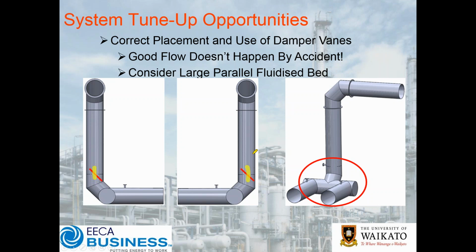And then what we were able to do was tune everything down with the VSD, and we had the airflow on both sides balanced with purely VSD control with a flow meter, even on both sides, to within less than 1% variation. So quite successful and effective compared to, I think it was a sort of 25% imbalance between the two previously. That was also able to save about $60,000 per annum in power savings.